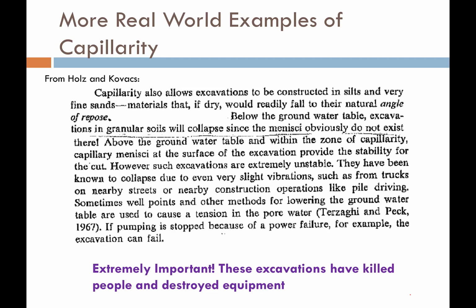And you don't need the soil to dry out. You can also have instances where vibrations from construction equipment can cause the tension from the water to break and can cause failures as well. So if you're involved in construction or construction methods, this is something you need to be aware of. Every time you choose to make an open cut or a vertical cut in moist granular soil, you're essentially gambling, because that soil is not able to sustain a steep or a vertical cut on its own unless it's moist.